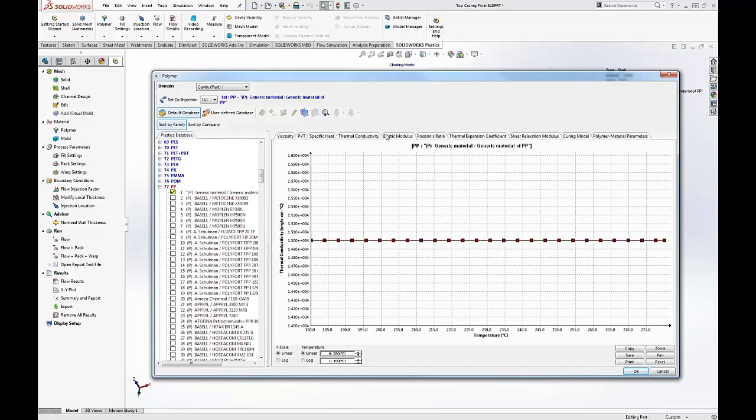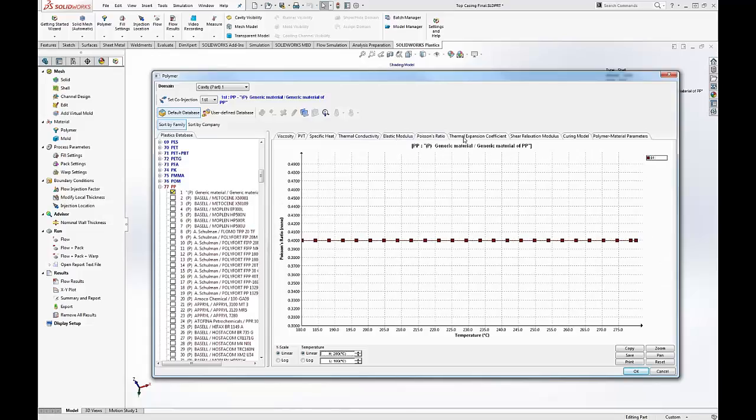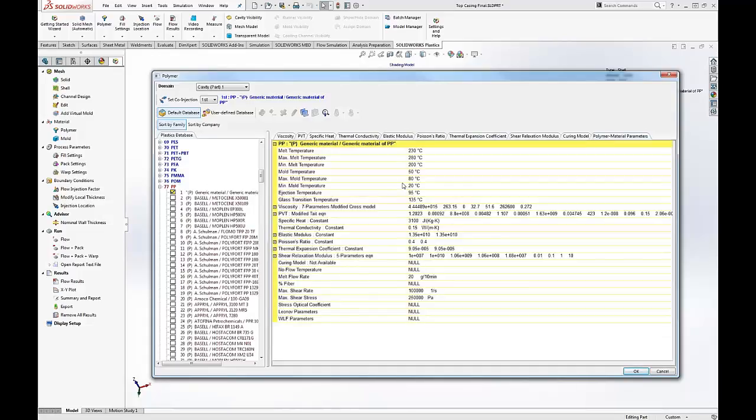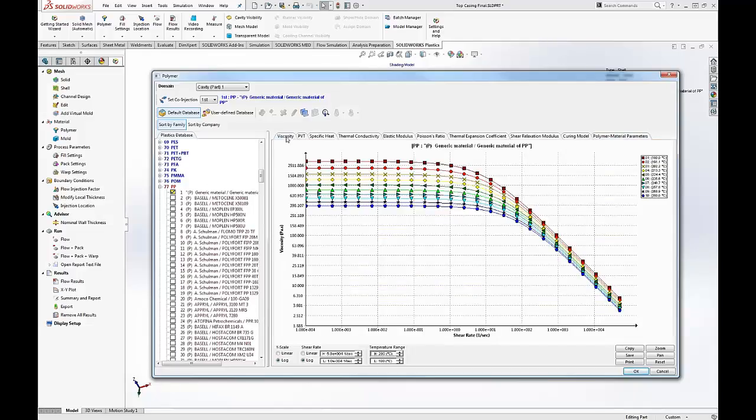Of course, other material properties, and of course the parameters. For example, here you can note the maximum melt temperature or the mold temperature. This is suggested by the material producer. Of course you can select your own material here if it's in the database. You can add your own material if you want, and also from this year you can have access to the Materiality web portal to download new materials as well, and it's updated every month.